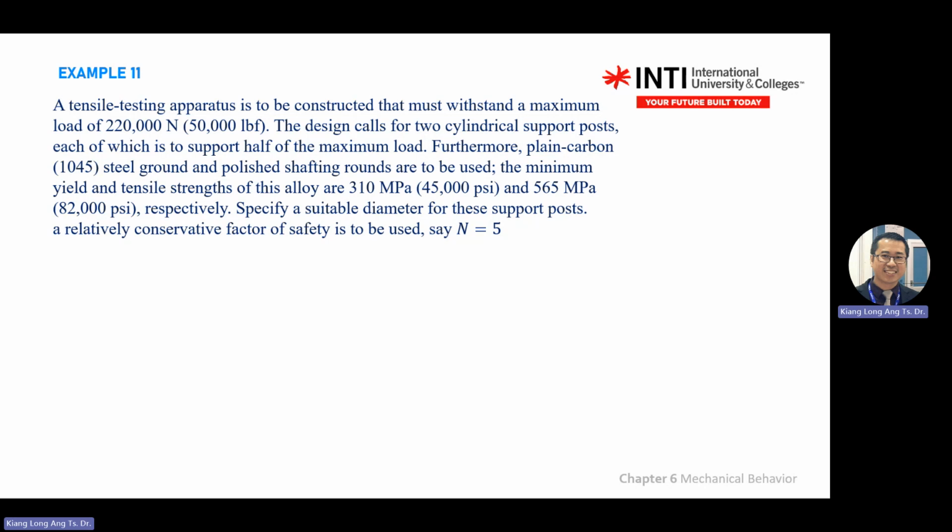For the application, let's say the lift cable is 100 kilonewton. So if you have a FOS of 2, you tell your customer this can only sustain 50 kilonewton.